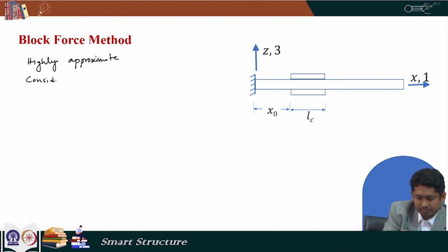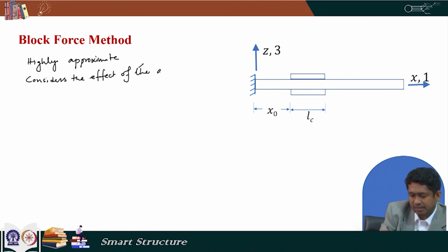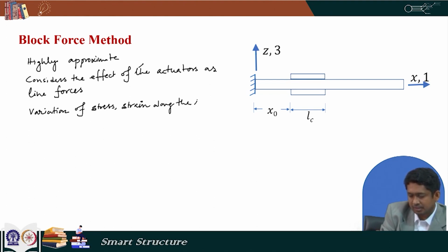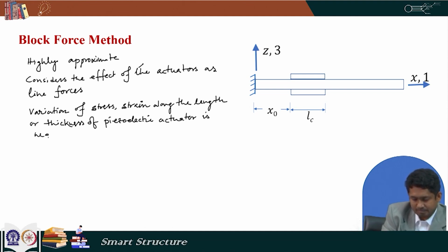It considers the effect of the actuators as line forces, and variation of stress, strain along the length or thickness of the piezoelectric actuator is neglected.